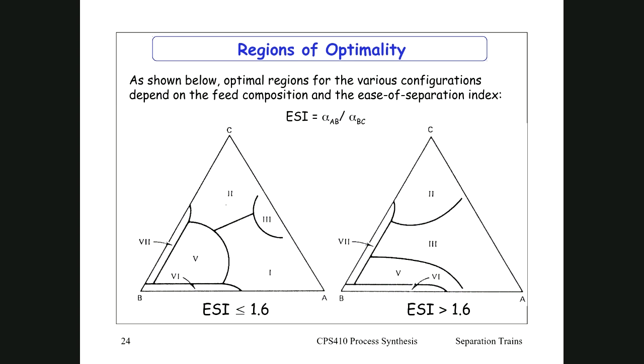So this is really straightforward. This is an algorithmic method. You can go and plug in the numbers, read it off the graph. One of the things you must just get used to doing is reading ternary graphs, and we'll be doing a lot more of that. But essentially, if you want to look at a line that contains equal amount of A, it is a line that runs from where the pointer is now across that way, equidistant from A. So this would be perhaps 75% A, and it runs there.